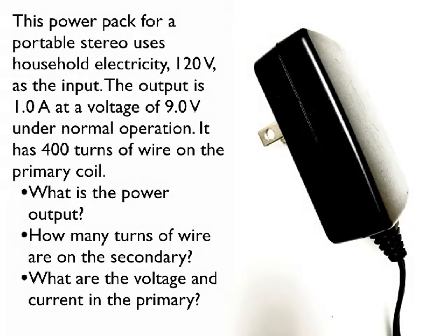You have many devices in your house that look like this, that you stick into wall outlets to run electronic devices. Because our electricity is AC, you can easily convert the voltage from one voltage to another using a transformer. This device has at its heart a transformer, and it tells us what the input is. It's 120 volts AC. Why? That's what's coming out of the wall.